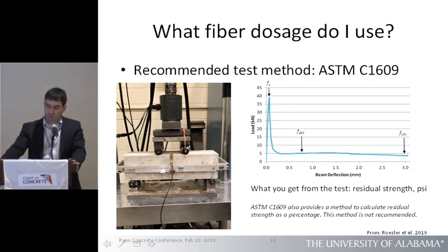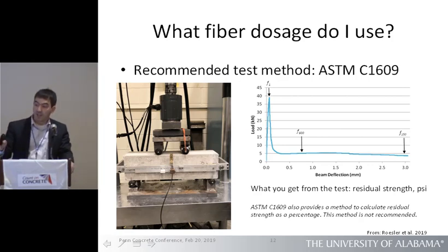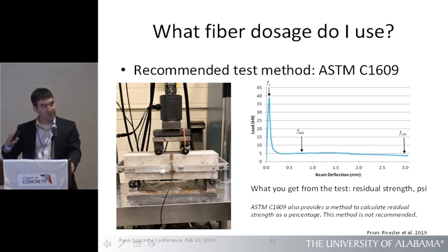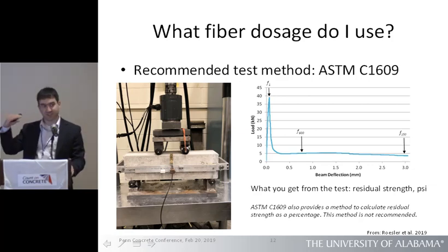And so a typical output from this test is shown on the right. You have your peak load, and that peak load is directly your MOR value. So if you run this test, you can get your flex value with this test. You don't have to run a separate test. But then you're capturing the behavior after it's cracked and it's starting to open. A good fiber will maintain a high level of load capacity as it opens more and more. A poor fiber or an inadequate dosage of fibers will not maintain as much load carrying capacity in this test.